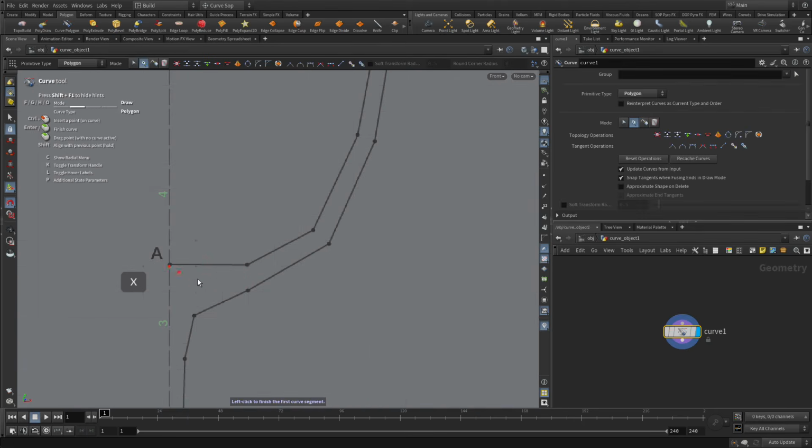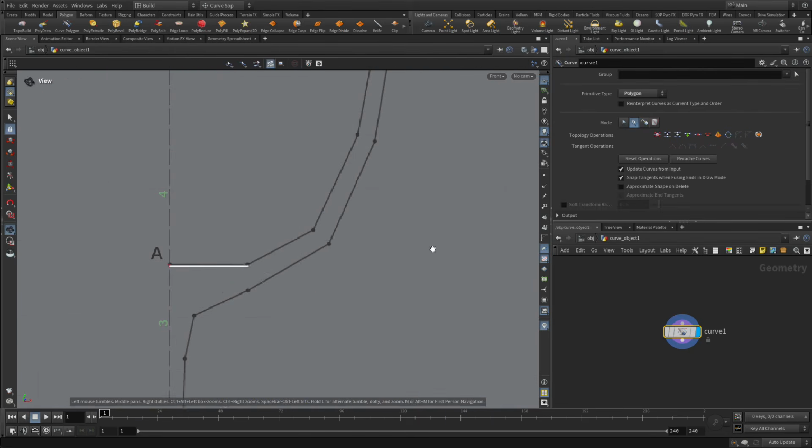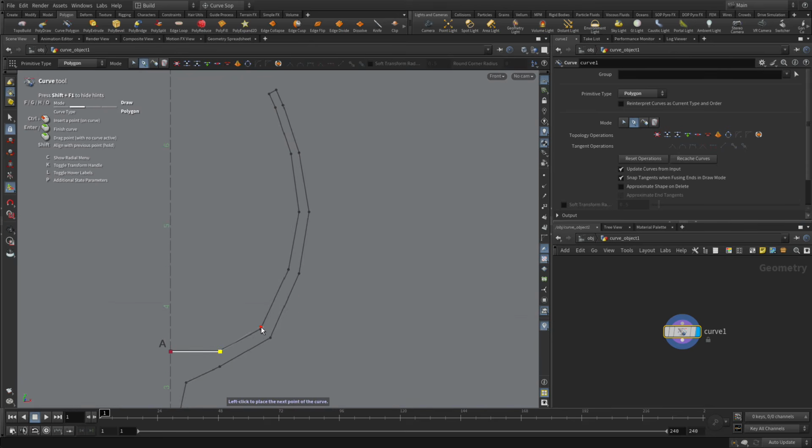Oh, we got to click again. So we click those two with the grid. Now let go of the X key. And now you don't have grid snapping on. So basically that's a volatile hotkey that allows you to temporarily turn it on. And we'll use it again in a minute.